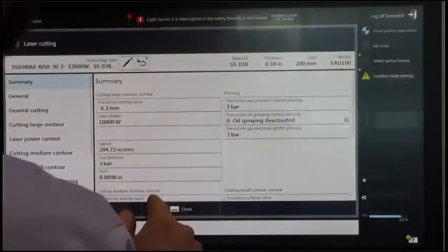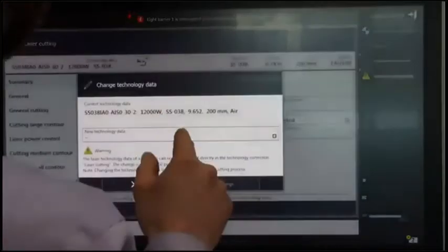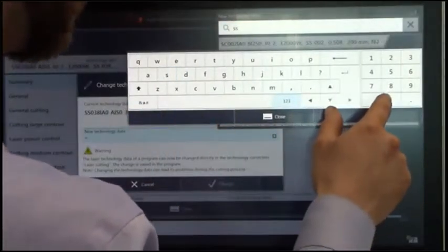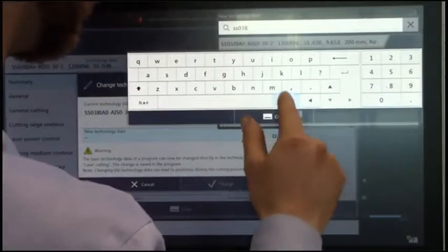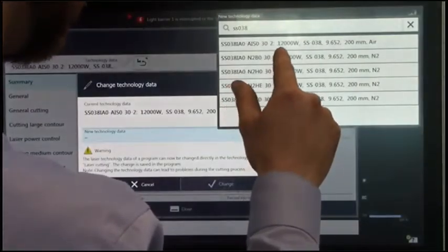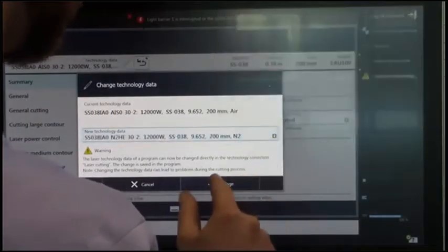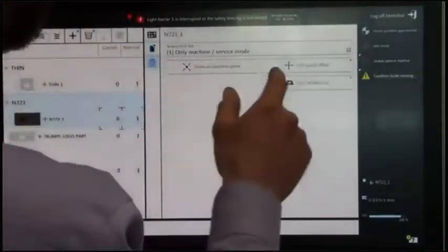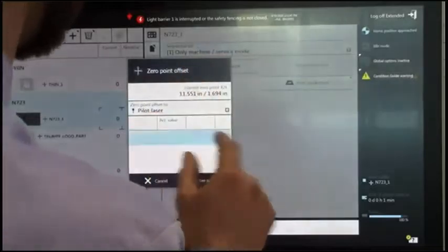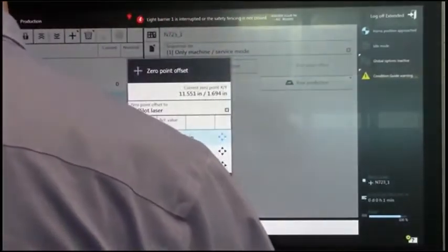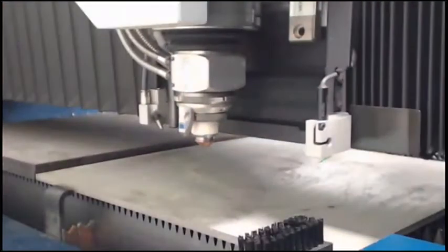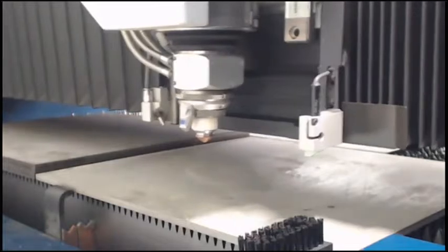With the Highspeed and the Highspeed Eco, rather than seeing really high pressures like 400 psi, 380 psi for the thicker stuff, your pressure is actually closer to 75, 80 psi. So it's really, really low. You have the ability to drastically expand the range. In fact, on stainless steel, you can go up to 1 inch. So the low pressure technology is really what allows us to increase the range without having to buy a special system.